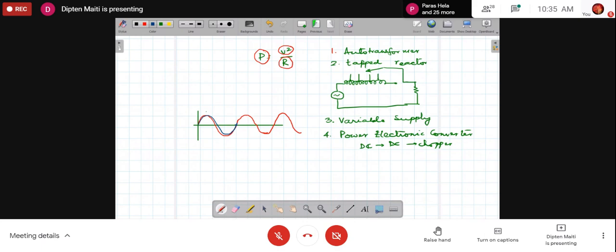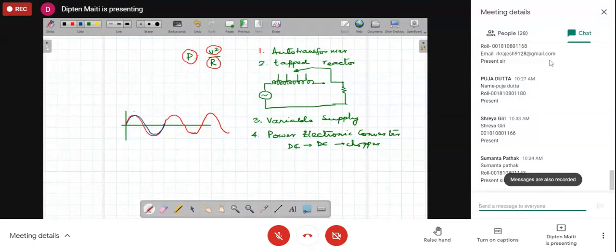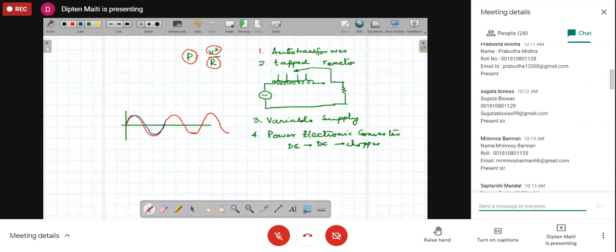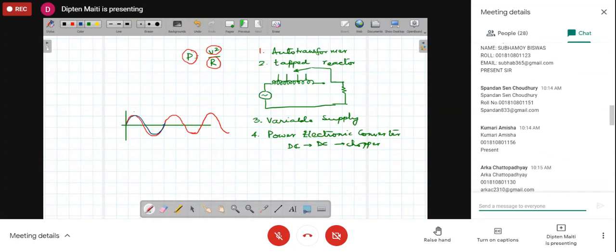Due to that, there may be what is sometimes called thermal shock. There may be problems because of the very high current. So even for the integral cycle control system, phase control is done for the initial few cycles or at starting. Then the system moves to the integral cycle control.